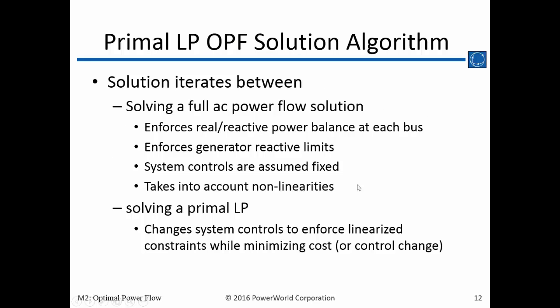So as we'll see too, when we do solutions in PowerWorld Simulator, it iterates between actually doing the power flow, which is the stuff that we looked at in the introductory course as far as solving a system of nonlinear equations for power balance, making sure generators are within their reactive power limits, that's in the voltage control loop, and things like that.